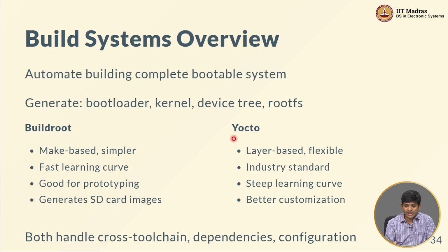Now, industry on the other hand prefers more complex systems which are capable of better customization. One of the most popular is what's called Yocto, right? It allows you to add on multiple layers and is a very flexible way of creating fairly complex boot systems. It's more or less an industry standard at this point, at least within the context of the Xilinx Zynq FPGAs, but that does not mean it's the only approach that can be used. It happens to be probably the most popular one currently in place. It does have a much steeper learning curve than Buildroot, which means you have to spend more time to actually get to grips with it.